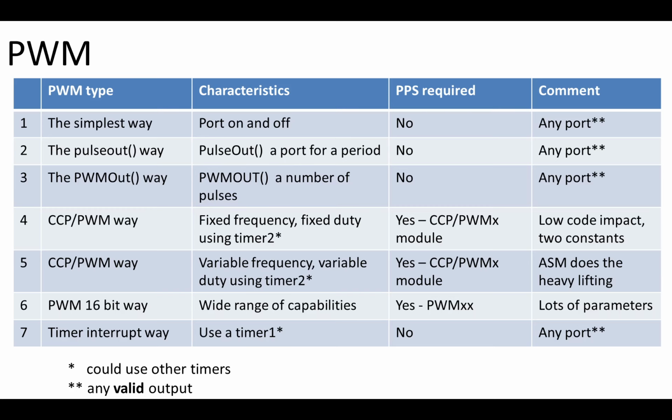Then you've got CCP PWM. And there is a method within GCBASIC that's called fixed frequency, fixed duty. And you need to set up the PPS. And the program does all the heavy lifting for you. It's just great. It just works. Very low impact, 2 constants, job done.